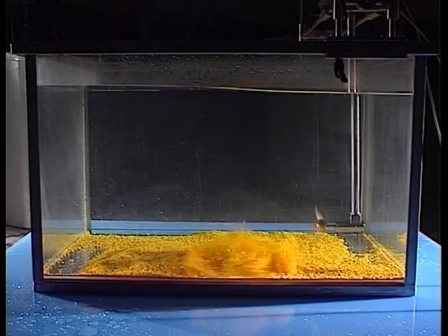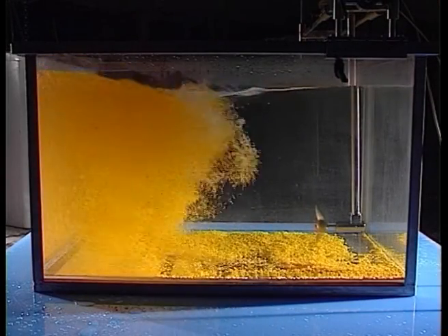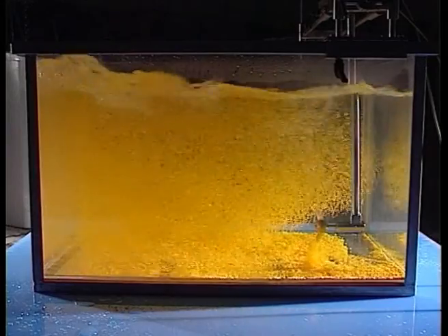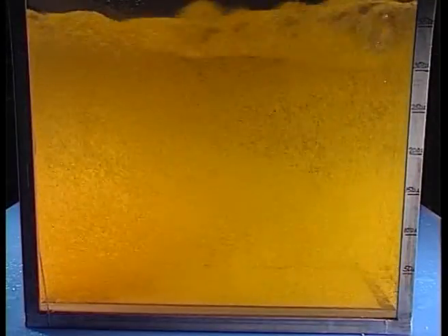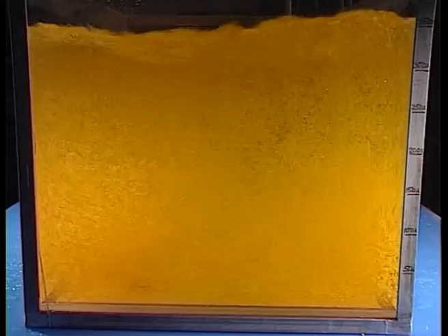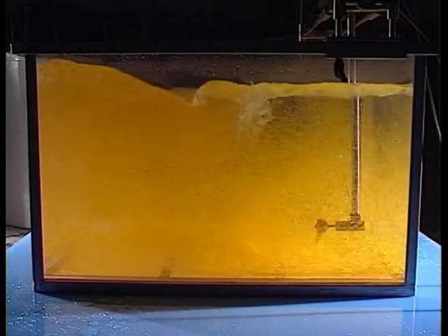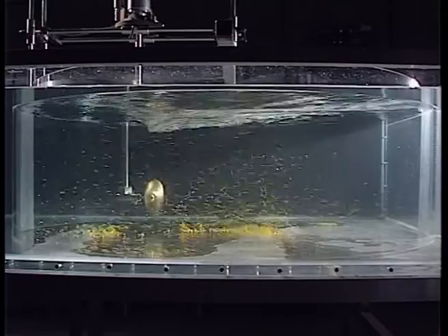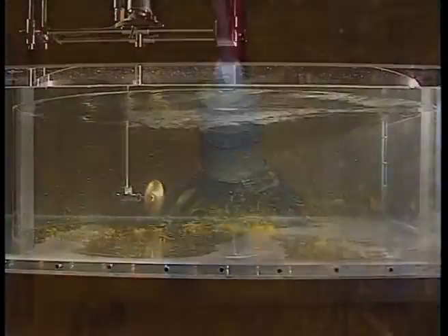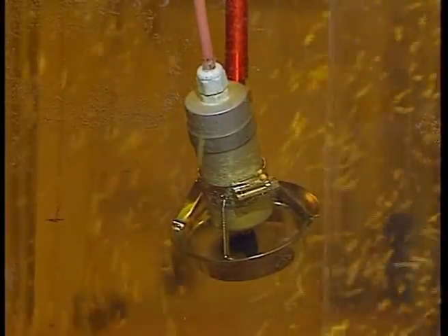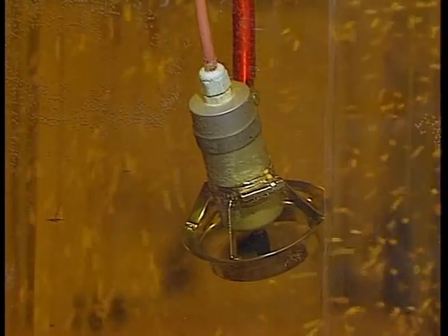Mixing is really about creating a motion or turbulence in the tank. This motion is often referred to as the bulk flow and is created by the thrust of an agitator. The amount of thrust needed to ensure good mixing is dependent on several parameters, including tank geometry, positioning of the agitator, and the type of liquid being mixed.